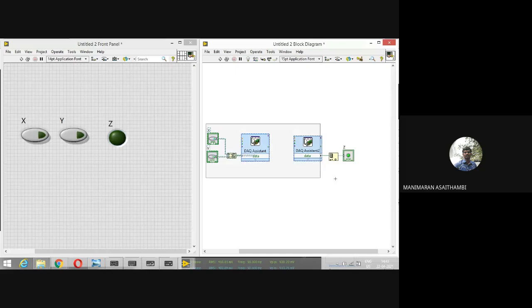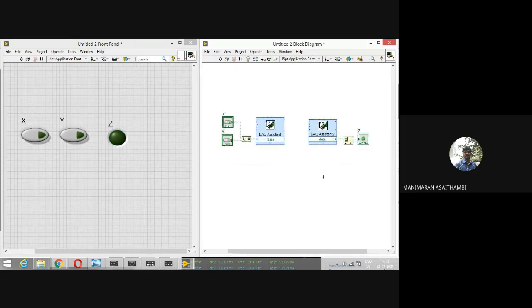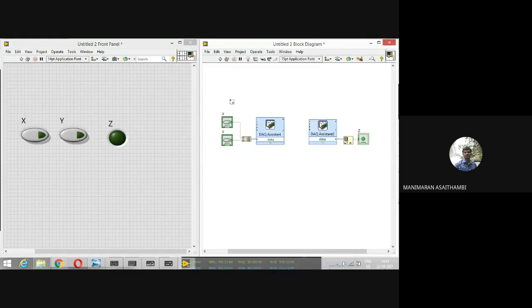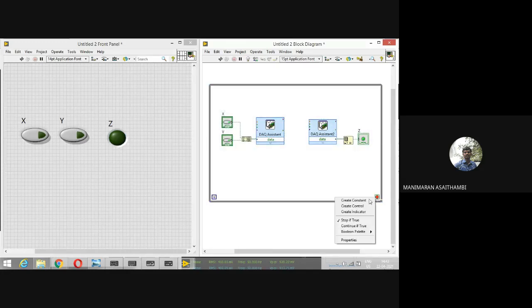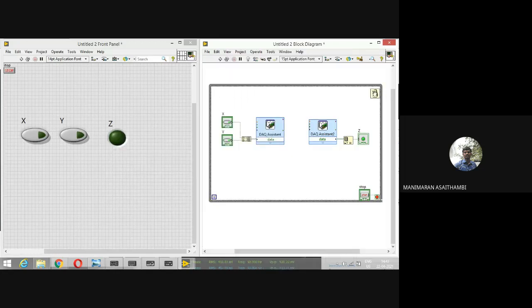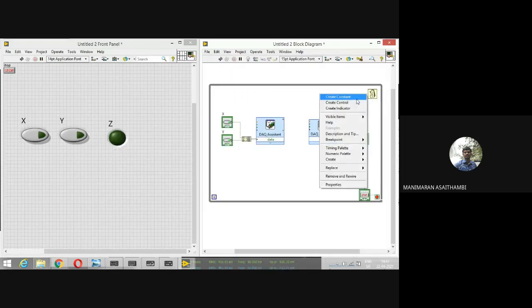Yeah. So now if you see there, I have combined the two Boolean inputs that I convert to data, which I am reading over there. So I want this code to run continuous. So yesterday you all have seen how to run a code continuous. So we'll be using a loop. So the same way I'm using a loop. I'll add a minimum time delay there.